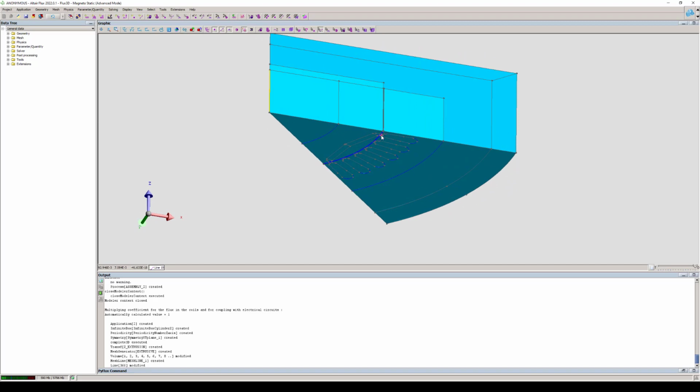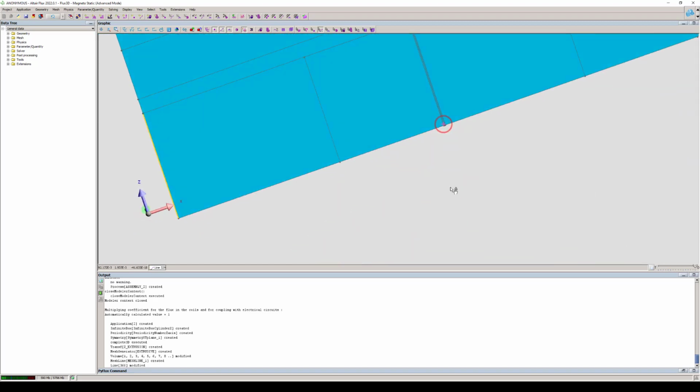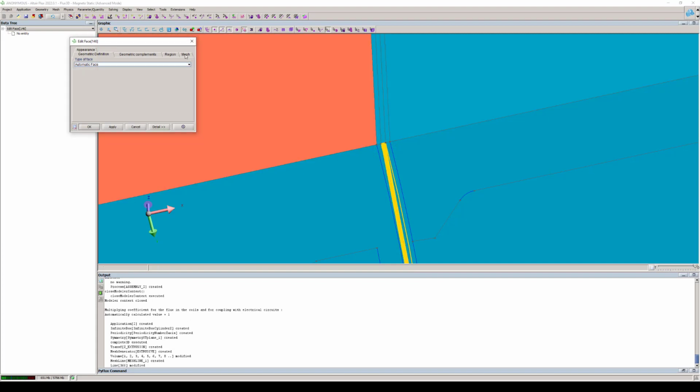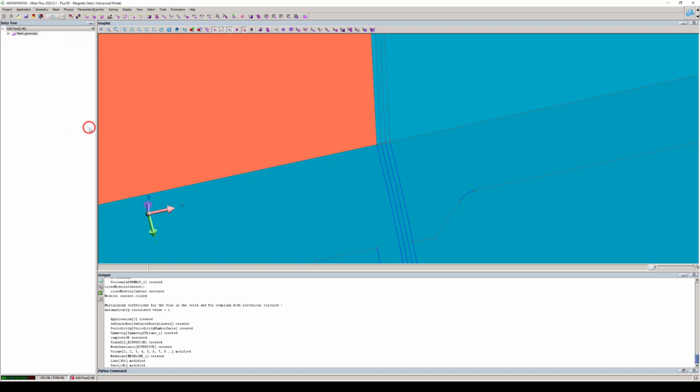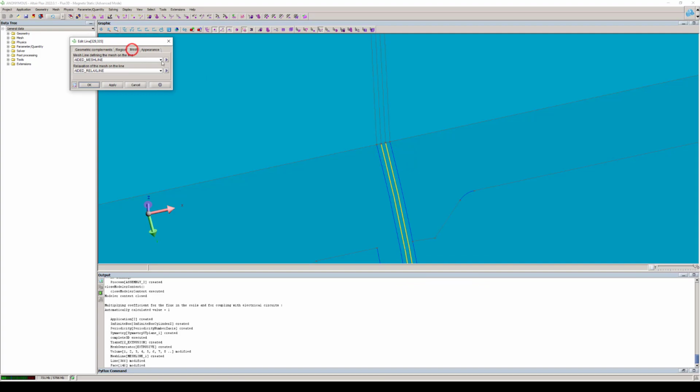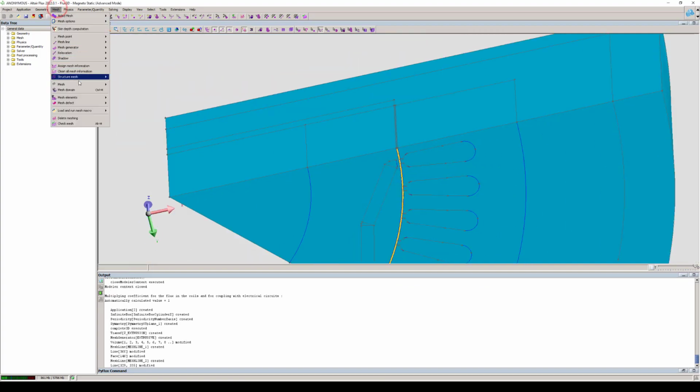Okay, and then one last thing we need to do in order to have the same mesh as we had in 2D. We have this face in the middle. So this is going to be extruded, but I also want it to be mapped to have the rectangular element as well. So I can go on this bottom face, mesh, and apply the mapped mesh. And again, as I did in 2D, I can just edit these two long lines and give them a different number of elements. Now, if I click on mesh,